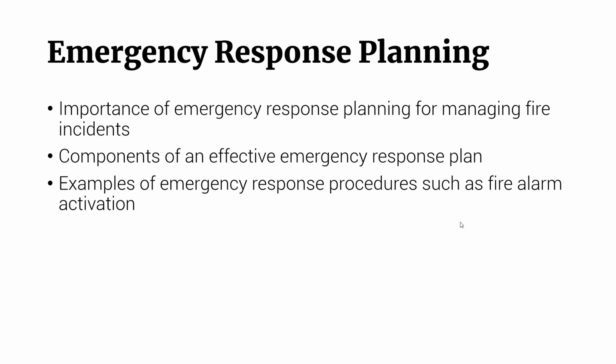The third one is evacuation. Direct occupants to evacuate the building using designated evacuation routes and assembly points. Again, usually these assembly points are open areas. Also, for your evacuation routes, make sure your markings showing where they will pass have no obstruction so they can see and read them right away. So those are the emergency response planning steps we need to do. Again, this depends on your DRRM or BFP and how their response plan goes during emergencies, especially during the event of fire.